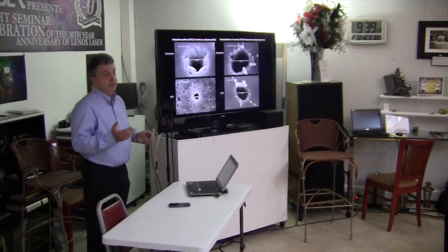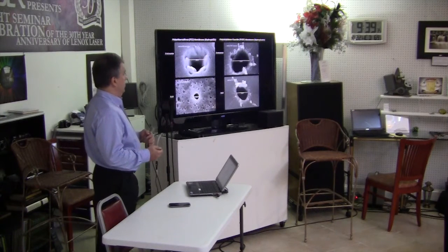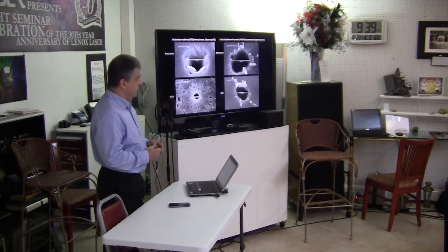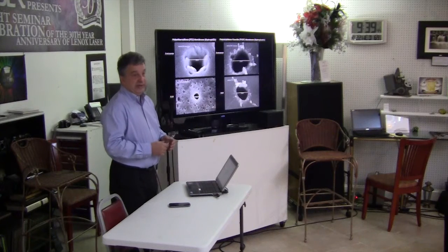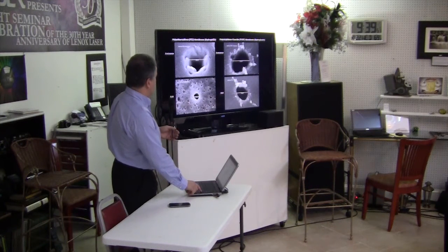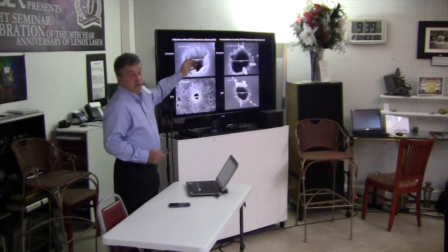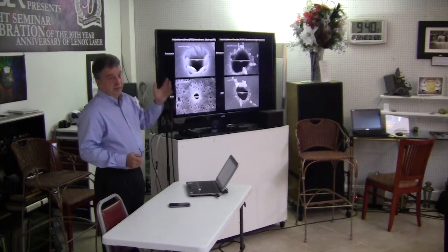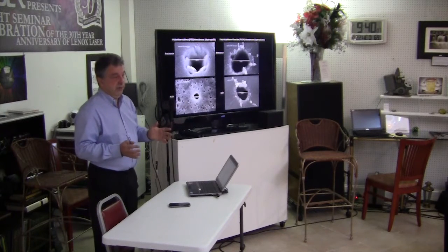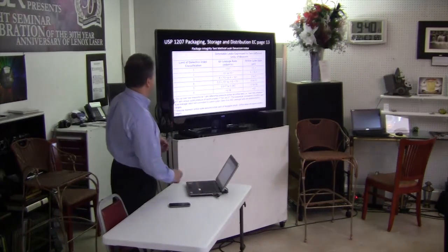So in this case, we're using cross correlation with all other methods. We're trying to use the optical microscope, we're trying to use electron SEM, we're trying to use the flow measurement devices, and it actually helps us to cross-calibrate those. Because depending on the length of the channel, the diameter of this hole is not the only limiting parameter. It's the impedance of the whole channel that becomes important in this case when measuring. And we are behooved to go in that area and do that with different instruments.